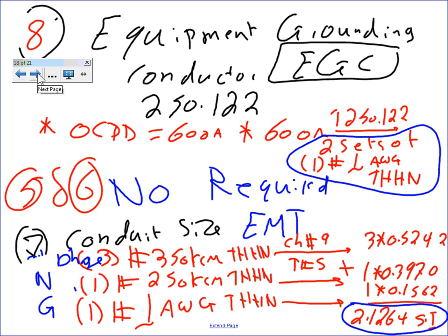Let's say it's 400 feet. If it's 400 feet, probably I have a voltage drop issue there. I might have to size based on voltage drop.